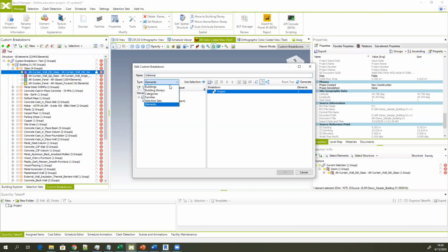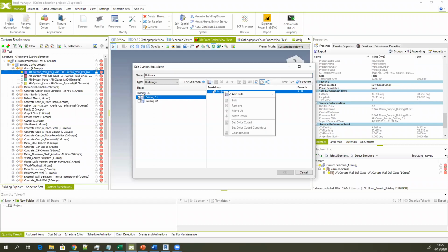And again, in this case, I'm going to include only one building, so you can see the difference when you use a specific selection from the left window. So in this case, I'm going to select only one building, building one, to be segregated, all elements from building one, according to not just basic available segregation methods based on the building level, category, family, but using some of the properties.